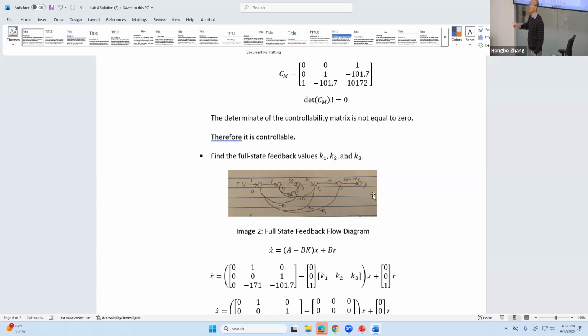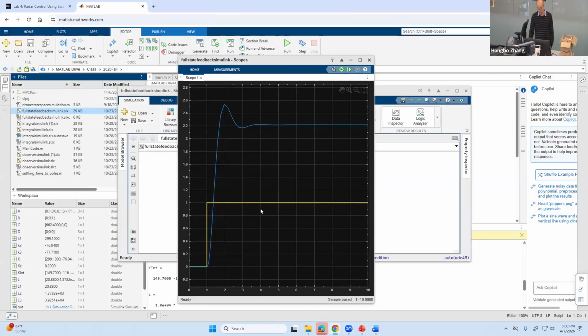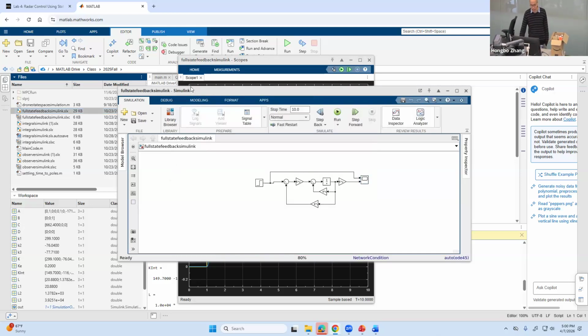That's why you need integral control, because of the error. And there's a pretty big error between your input and output. You see what I mean? The input is this, your output is like that. A huge error there, okay? But it's definitely stable, right? It's not diverging, right? It's stabilized. So that's one.